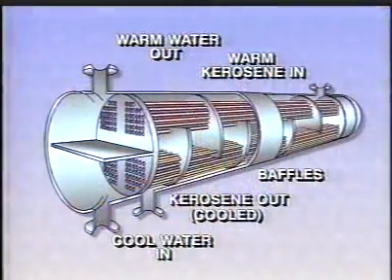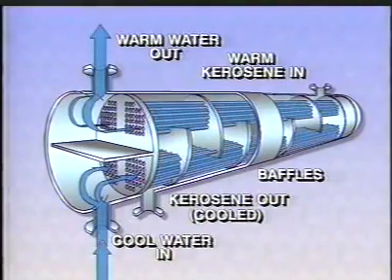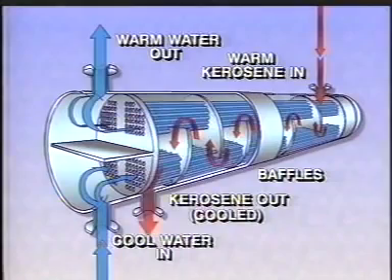Coolers are heat exchangers too. As the name implies, coolers lower the temperature of the liquid or vapor. In the next example, kerosene is being cooled before going to storage. Cooling water passes through the exchanger twice, while the kerosene makes only a single pass.